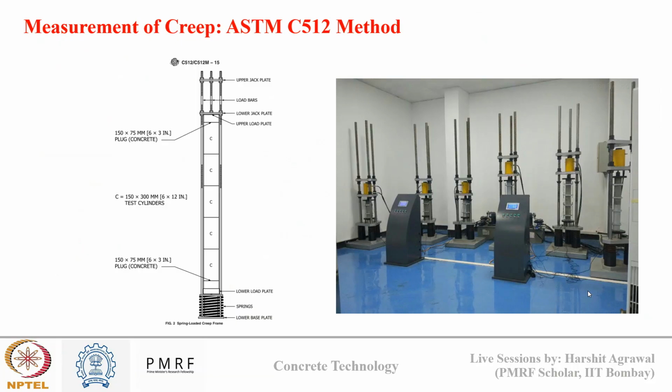After prediction, we talked about how creep is measured in the laboratory based on the ASTM C512 method, where we have concrete cylinders which are subjected to sustained loading conditions, and deformation is determined after different time intervals using a deflectometer.